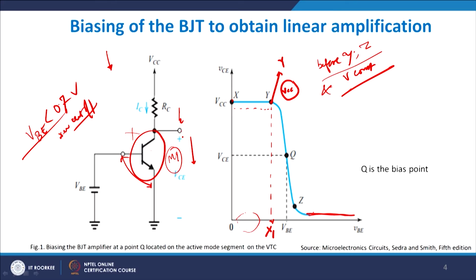Now, you see we define the Q point, quiescent point, as a point which is highly stable, right. So, these two are the definitions of the Q point which is seen in front of you, which means that this Q point, by application of an external bias, can move up and down, but within the linear regions of the amplification process. You should be very careful as far as designing is concerned, that you cannot let the Q move anywhere it likes, but only across the small signal domain, such that you get a large amplification in this area.